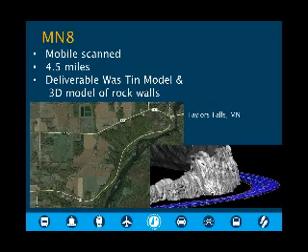But once again, the profile through there was not what it was when they had built the road. A lot of it is due to the road sliding a little bit downhill. It's cut, as you can see in the lower right, out of a cliff. And some of the fill on the downhill side has moved. And so they needed to know better where this road is. We had a lot of traffic coming out of Wisconsin onto this roadway, so we needed a good TIN model for that. We also got the rock face along there.